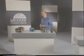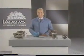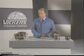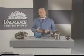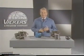Pumps fall into two basic categories: positive displacement and non-positive. Non-positive pumps are used primarily for circulating or transferring fluids. Examples would be the water pump on an automobile engine, or one used in a dishwasher or washing machine. Let's look at a schematic.